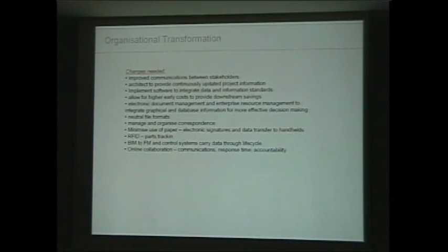one of the things that happened with Revit 9 was IFC parameters had to be fed into a lot of the basic families to allow users to start to play with it. And what we found was that the parameters that are available as part of the IFC system are not as extensive as the parameters that you can have in Revit. So that if you have a door, the IFC can understand single leaf, left opening, single leaf, right opening, double leaf. And that's virtually it. And that's not really enough of a description, given what you can do to that door in Revit.